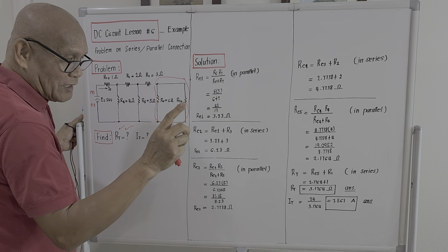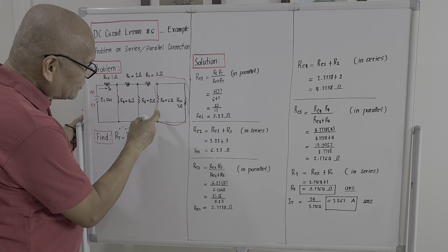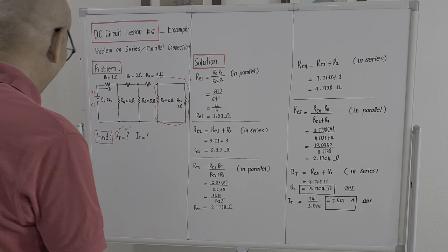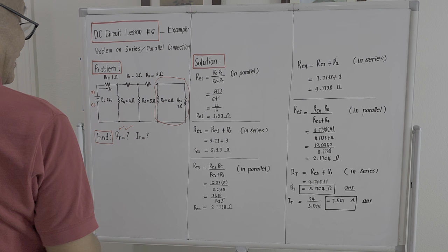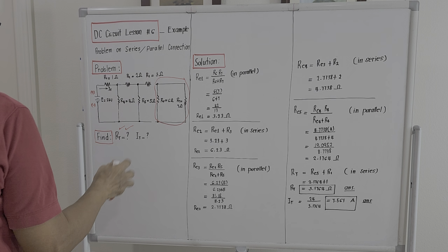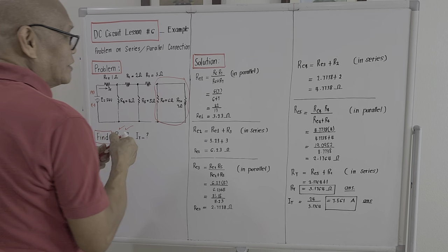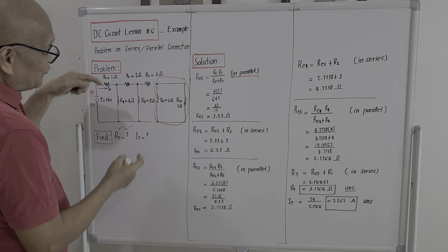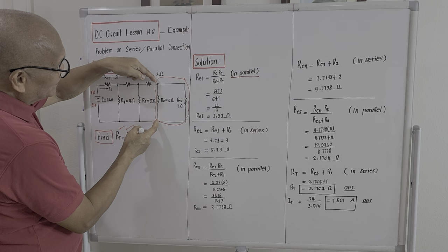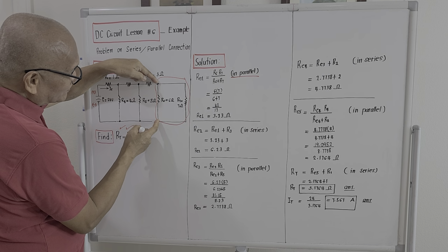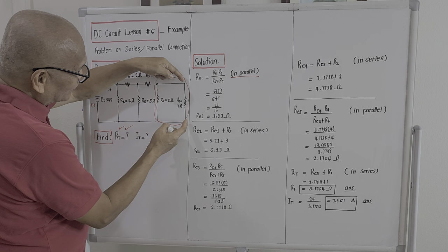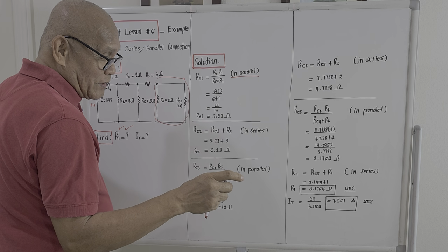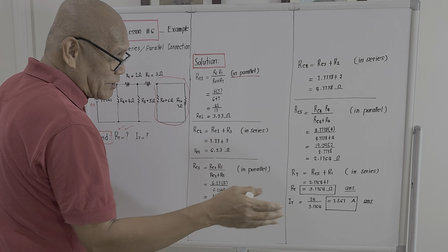And we will be asking ourselves, what is the connection of R sub 6 and R sub 7? What do you think, guys? I think the connection between R6 and R sub 7 is actually they are in parallel. Why? Because if we try to get our voltmeter here, the voltage across R sub 6 will be equal to the voltage across R sub 7. And for a parallel connection, the voltage should be the same. So if they are the same, they are in parallel.